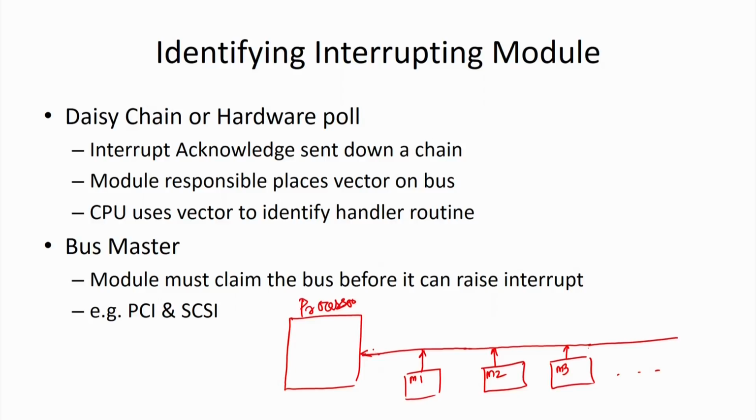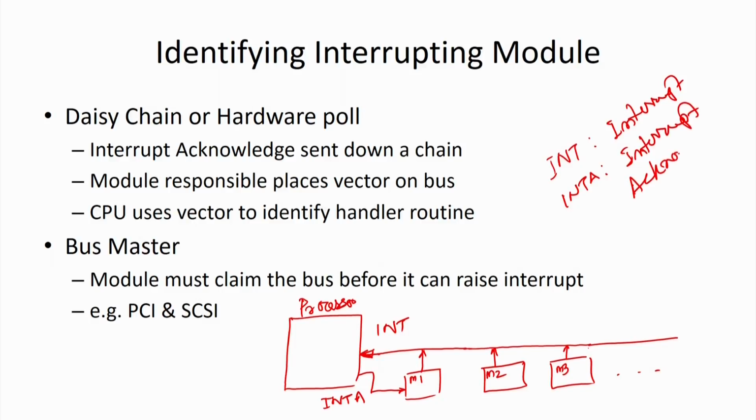When the processor is getting an interrupt, then it should give service to the device. So, most processors have one line called interrupt acknowledgement. Basically this is the terminology we use: INT says that this is the interrupt line, and INTA is the interrupt acknowledgement. Okay. So, these are the two lines. Now when the processor is going to service the interrupting devices, it will set this interrupt acknowledgement to 1. It says that now the processor is ready to give service.